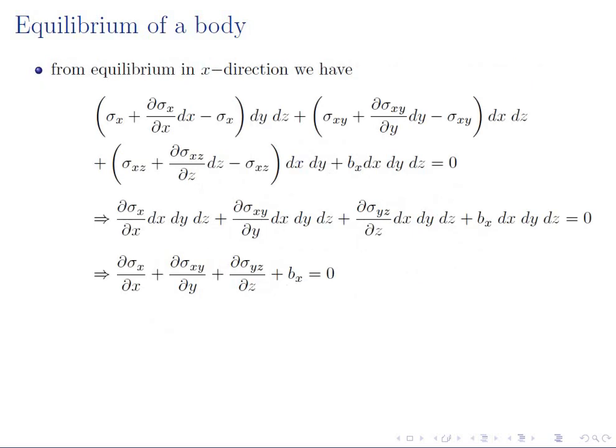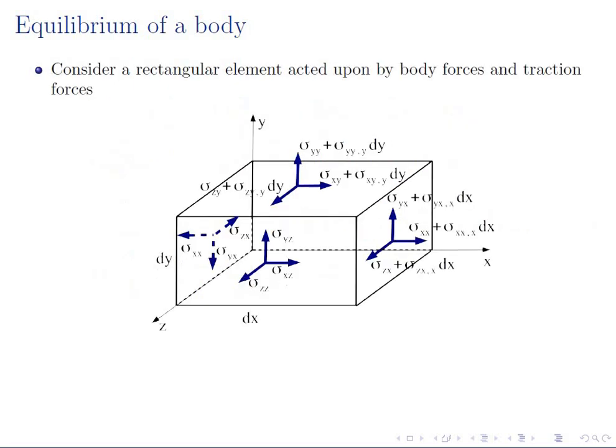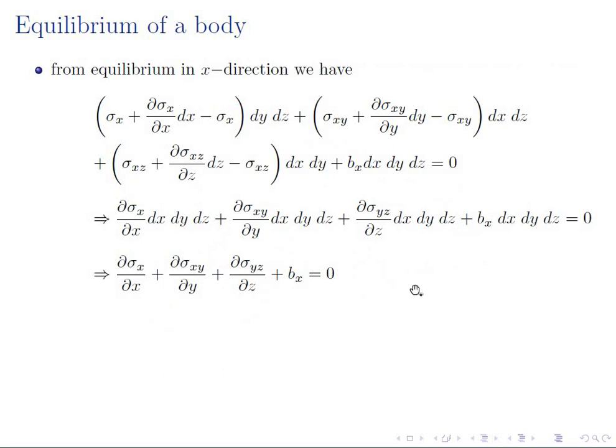Let's look into the equilibrium of forces in the x direction. Sum up all the horizontal forces. So the force created by sigma xx and the force created by sigma xx plus sigma xx comma x dx, multiplied with the corresponding areas.